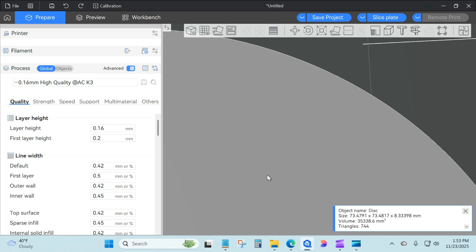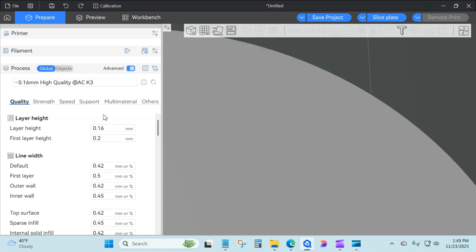Unfortunately, speed becomes the sacrifice when aiming for the best quality. The higher quality you want, the lower the layer height, and the longer it will take to print. Of course, you can always bump your speed up to like sport mode or something, but that is not advisable, especially if your model has delicate features or if you're printing with standard material and not high-speed material, you might encounter some failures. So at your own risk if you want to bump up the speed and use a lower layer height. But this is a hobby.